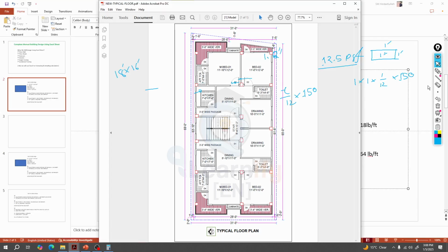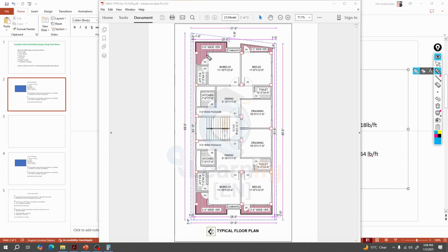We are designing that slab, right? As we are designing this slab, we have to check which portion of partition wall is acting on the slab. See, here and here, only those two walls are on our slab, and the other walls around it are not on our slab, where our other wall is over the beam. Okay, now from that point to that point, what is the length?